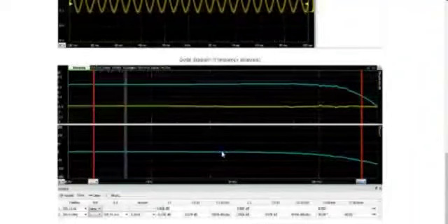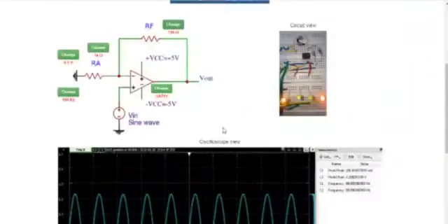Let's start the analysis with Ra of 1 kΩ, Rf of 10 kΩ, voltage of 100 mV and frequency of 100 Hz with μA741 op-amp, which is having relatively lower performance parameters. With the input sine wave frequency as 100 Hz, observe the peak-to-peak amplitude of input 208 mV and output 2.2 V respectively, thus confirming gain of nearly 11 in magnitude. The output signal is in phase with that of input.